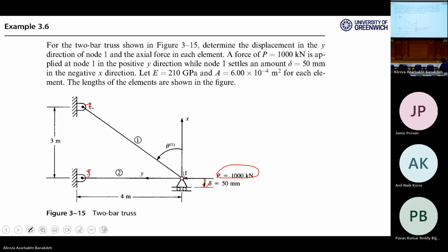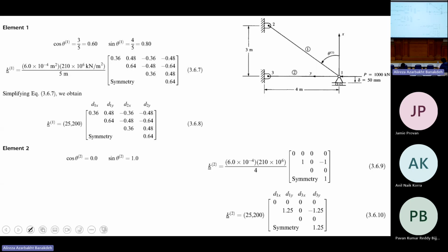I know the individual stiffness matrix for each element is 2 by 2 in the local coordinate system and 4 by 4 in the global coordinate system. So I start by assembling the individual stiffness matrix for element 1, 2, like this is for element 1. So this is E, this is A, this is L, EA over L, right?